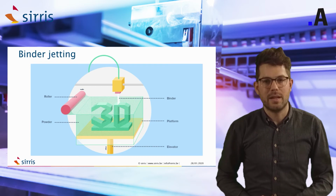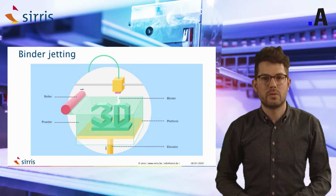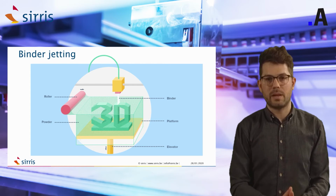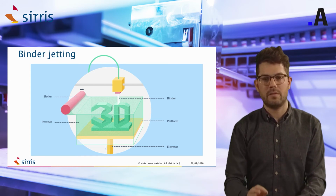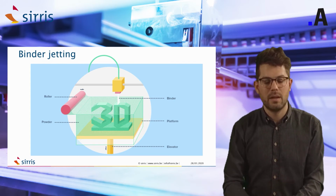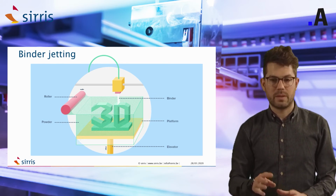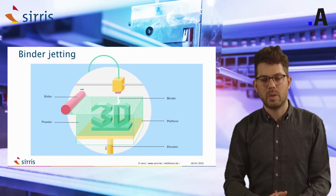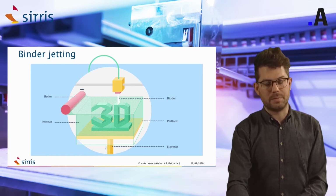Then we come to the next technology, binder jetting. This is one of the technologies we use to print powders. How does it work? In fact, we spread a layer of powder, and this layer of powder is afterwards glued together with a binder. After this step, those printed or glued powder parts are taken out of the printing bed, and they are infiltrated with a second material.